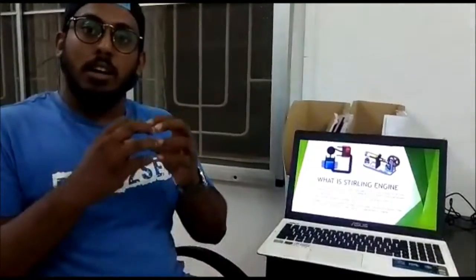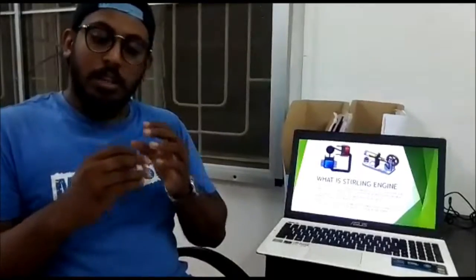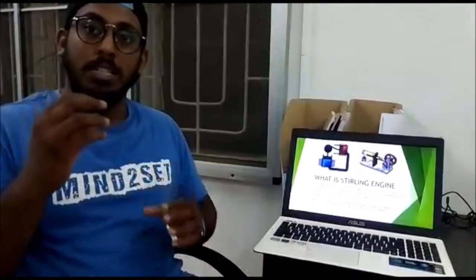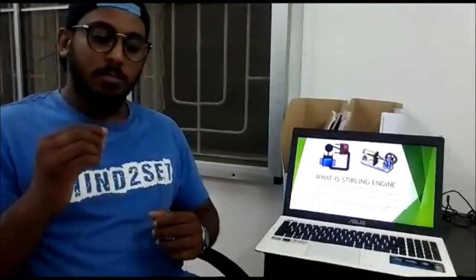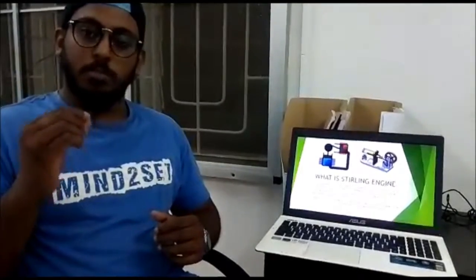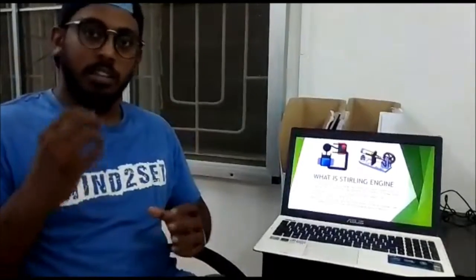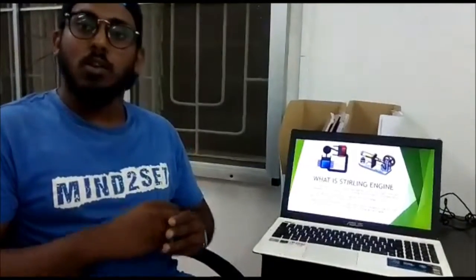A Stirling engine is a heat engine that operates by cyclic compression and expansion of air or other gases at different temperatures, which means the Stirling engine operates as a regenerative heat engine with a permanent substance like gases inside the system. In thermodynamics, this is a system in which the working fluid is permanently contained within the system. The gases are permanent inside the engine and operate there.